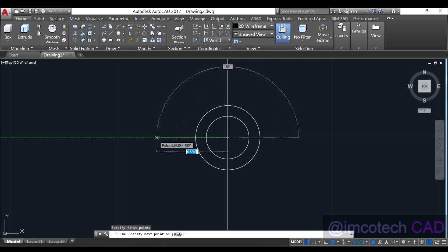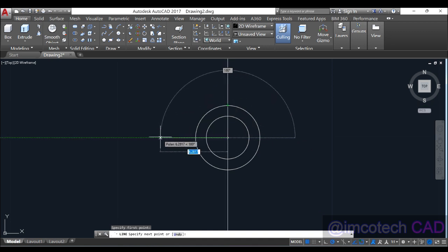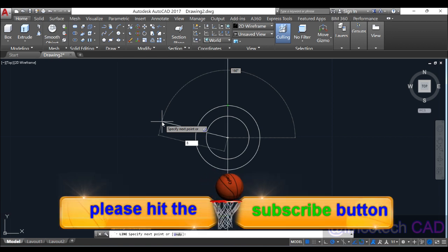Meaning at this point we are at 180 degrees because you are starting from here. Now remove 20 from that 180, I will have 160. So I can just say 8 as the unit of this line. Then hold shift on your keyboard, less than, and write 160.